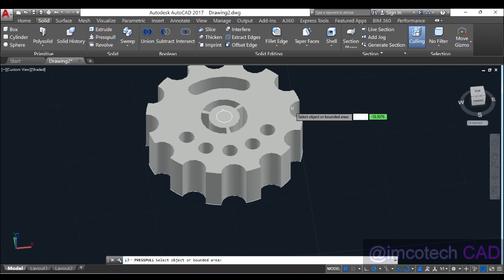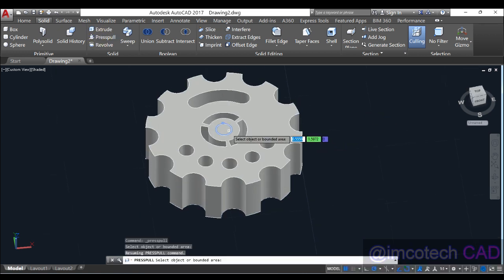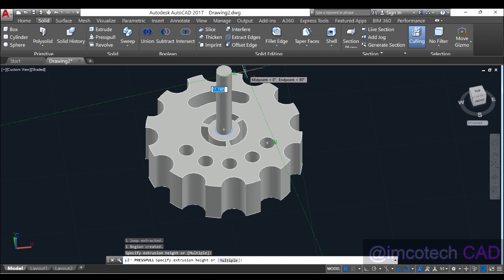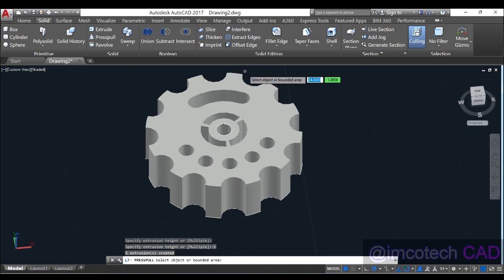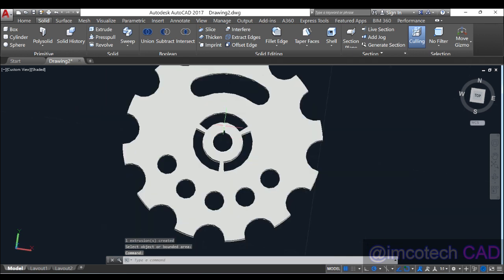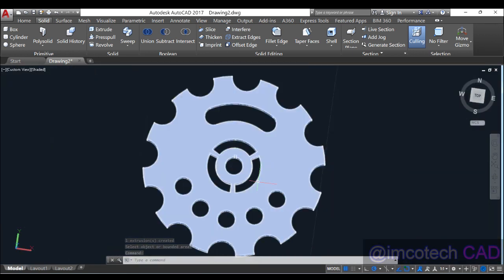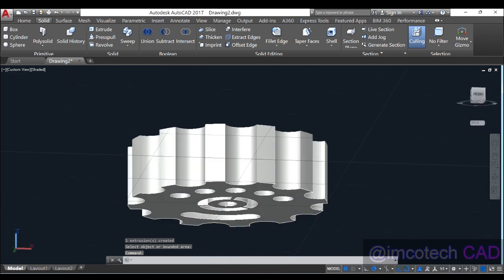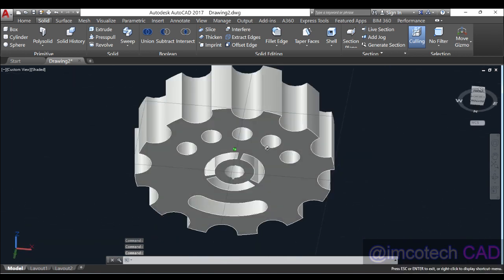So look at the reverse press pull we're going to do here. We will tap on this to press pull this, but instead of taking it up, we know that the whole length of this design is 6 units, right? There is no need to take it down and start subtracting again. Let's take it up and write -6 units. It will automatically drill a hole in the opposite direction. Okay, so we have that. Yes, the lock is too small, I know, it's not part of the design, so subsequent videos will be much better than this. Thank you for watching.